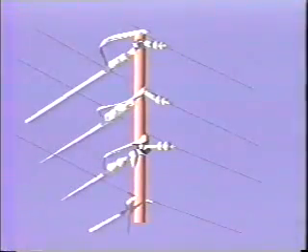When the conductor angle is between 30 and 60 degrees, the construction changes to a running corner, with the three conductors arranged in a vertical configuration. A taller pole than that used on single-phase is required for the vertical spacing.